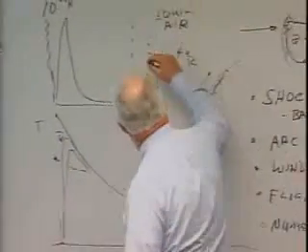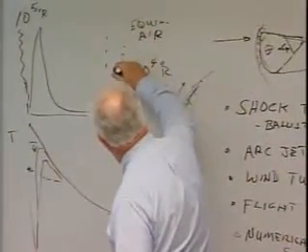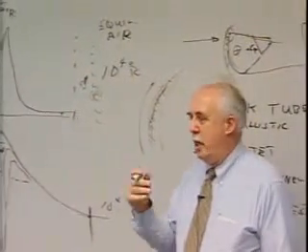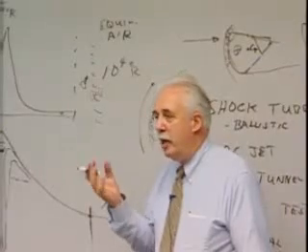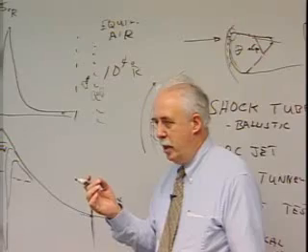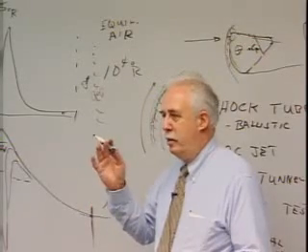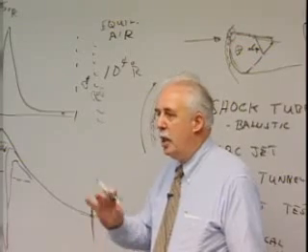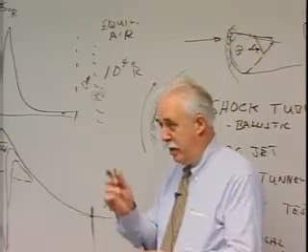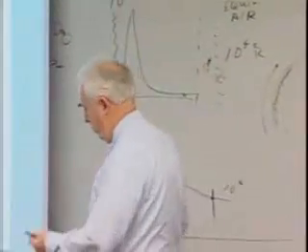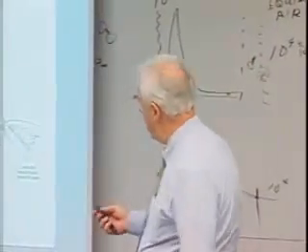If I have atoms coming into the surface, and they are, if you want for discussion, absorbed on the surface, and then another atom comes in, recombines and forms a molecule that releases that energy, that is a catalytic surface. Okay? So you have sort of two limits, a completely catalytic surface and a non-catalytic surface in a non-equilibrium environment. And that's very significant on shuttle, and you'll see that in some data I'm going to show here in a short while. Okay.